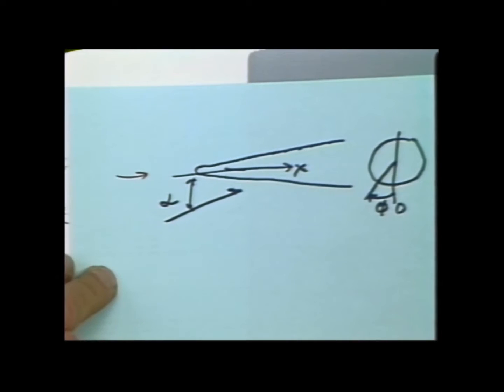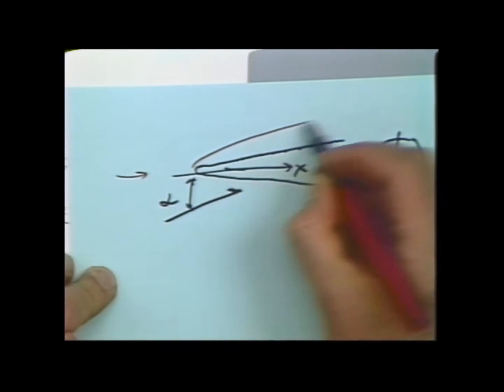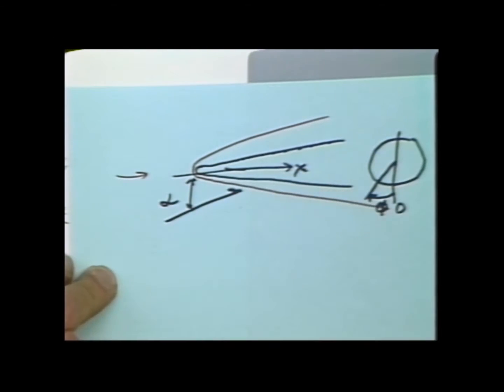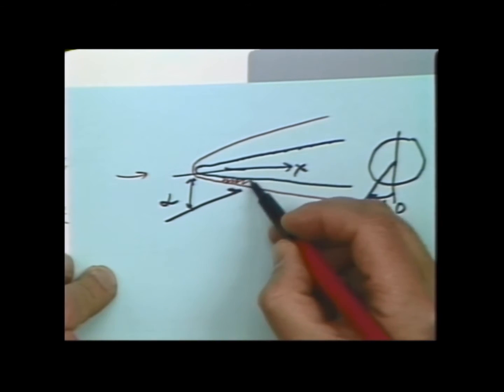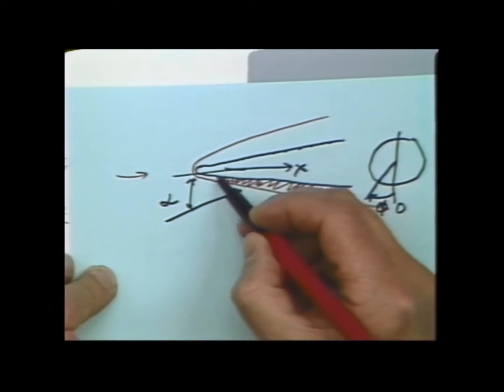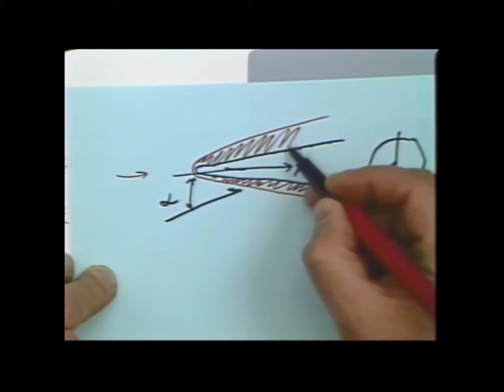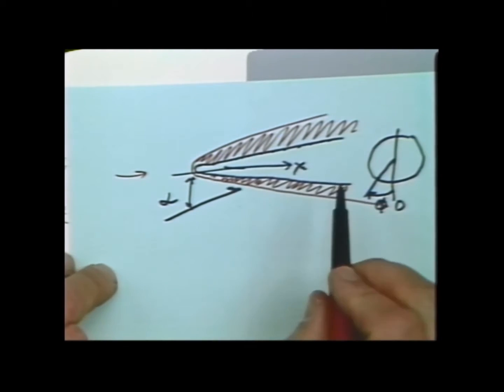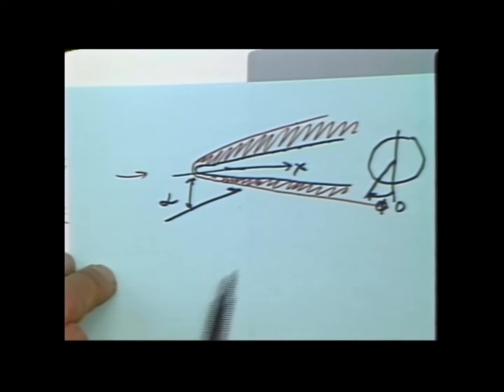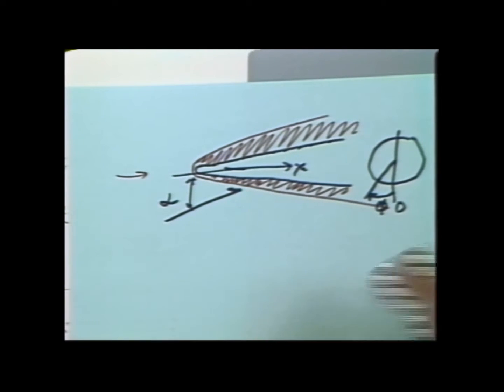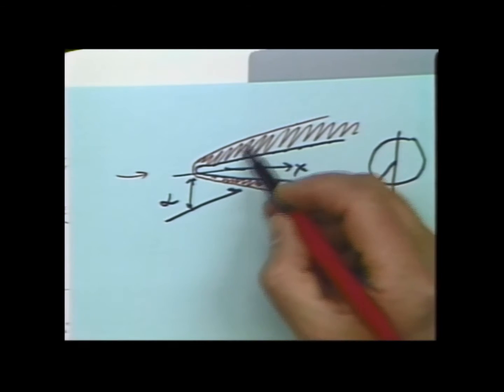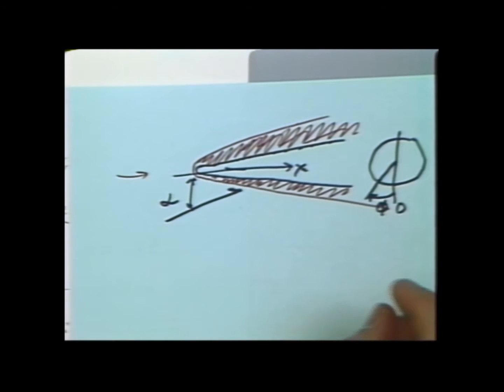When you deal with the, let me draw a picture here. Here's our blunted cone, and it's at hypersonic speeds. And I'm going to draw the shock wave here over this cone. It's at an angle of attack. This whole shock layer between the shock wave and the body, when you deal with the parabolized Navier-Stokes equations, the whole thing is being treated as a viscous flow, all the way from the body to the shock wave. There is no special consideration of a boundary layer, no special consideration of an inviscid flow. The whole thing is viscous, at least insofar as the equations are concerned.